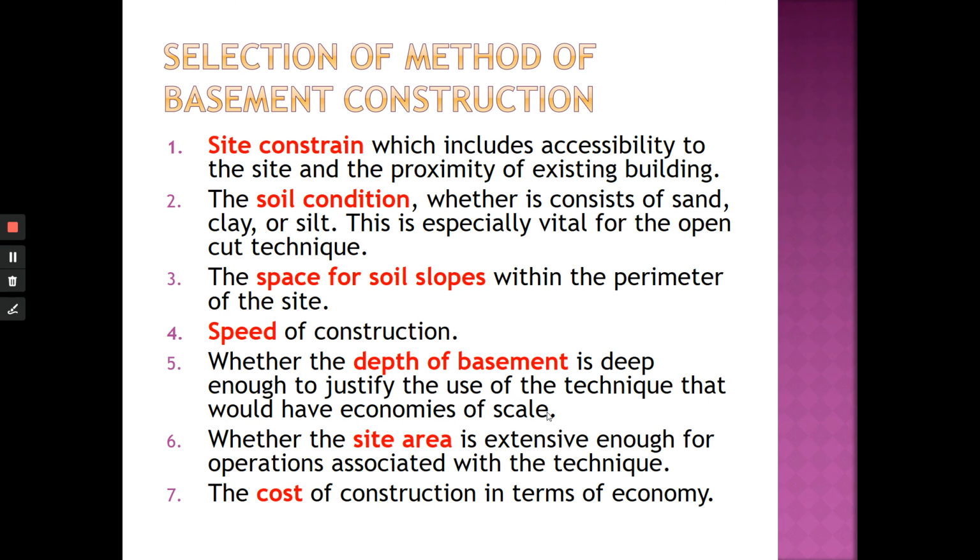But if you have more than one level, like say 2 levels, you want to do open cut. Would it be suitable? What do you think? Just imagine 2-3 levels of basement, 4 levels of basement. You want to dig all the slopes down to that level. It would take a lot of time, a lot of money, and waste a lot of energy. So this is cut and cover. So you just cut and cover.